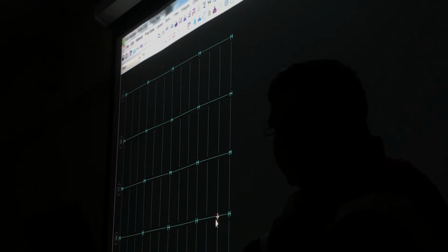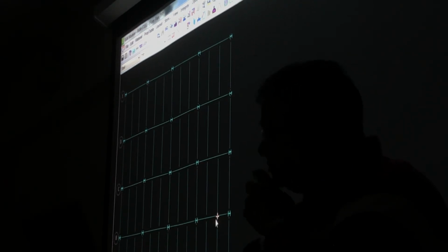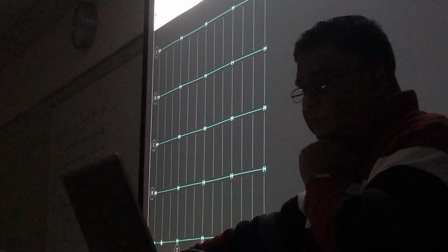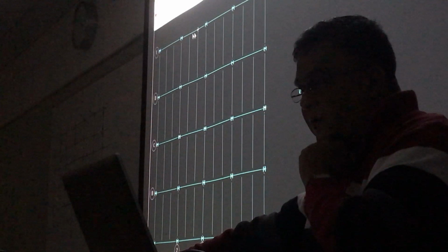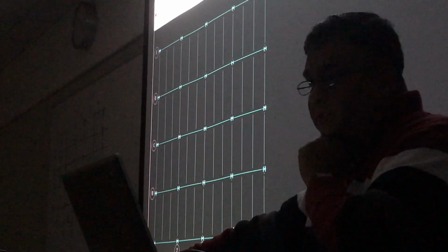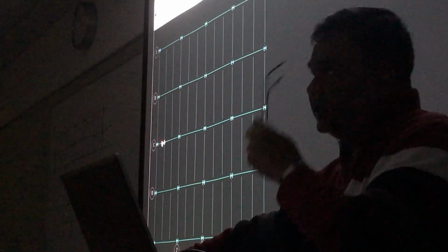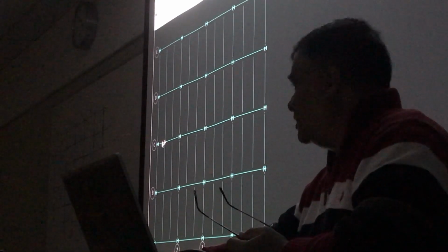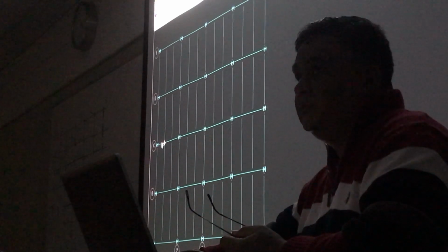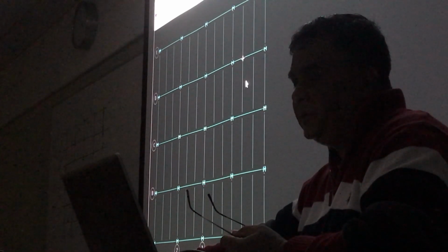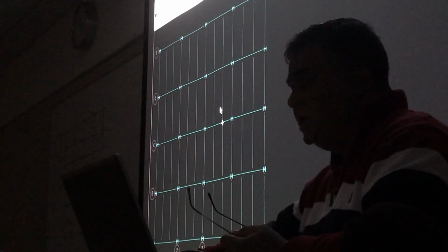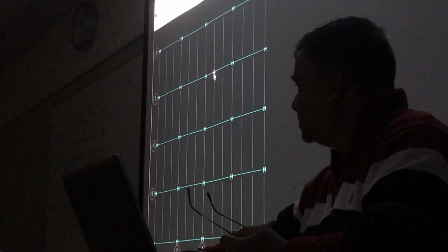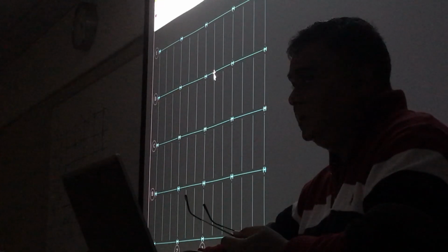The next step is I know that I have moment frames and brace frames, right? So I have moment frames these three, this one, and I have moment frames here, and I have brace frames these two. Okay, so let's give them. Now, moment frames or brace frames, what are those? Moment frames is basically beams and columns. The only difference is their connection, and they're supposed to take lateral loads instead of gravity loads. So all of these in the middle are gravity loads, and the connection between this beam and this beam, and that beam is all simple connection, bolted connection. That makes my life easy.